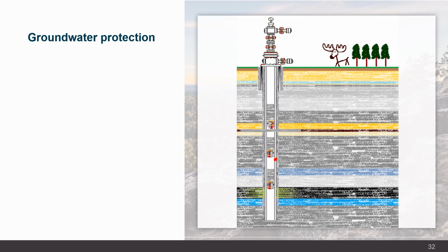In some rare cases, particularly for older wells where the production casing was not cemented to surface, additional remediation to protect groundwater might be required. Similarly to surface casing vent flows and gas migration, merely placing a bridge plug and cement cap inside the casing would not solve the underlying issue.